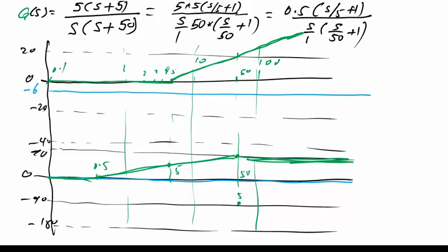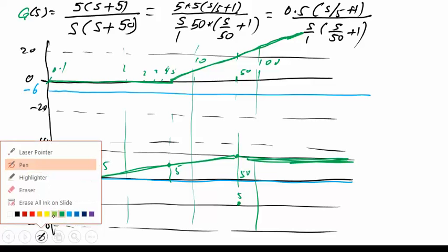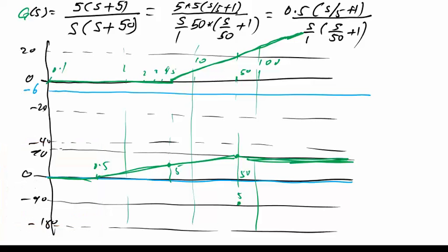So I will switch to another color, and let me do this color, okay? So how do we do it? You want to help him? Just help him. Just a straight line. So this is a straight line with a slope of minus 20 dB. See, here we said this is the 20 dB, so the minus 20 dB. So this is a straight line across all frequencies. And what would be the phase angle?